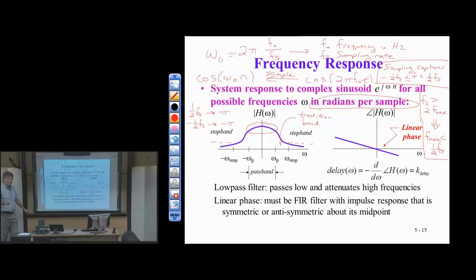It's almost a don't care region. It kind of is, except that we don't want it to go above 1, because now we're amplifying frequencies in the transition band. That doesn't make a lot of sense, because then it actually would be another passband. Anyway, the transition band has some flexibility. All right, so that's the magnitude response.